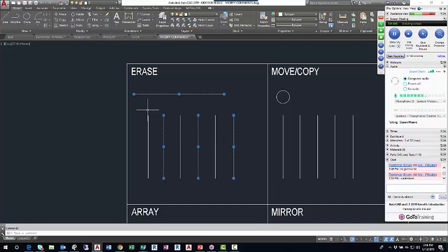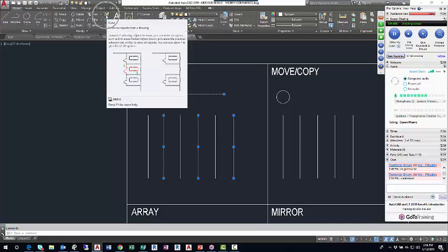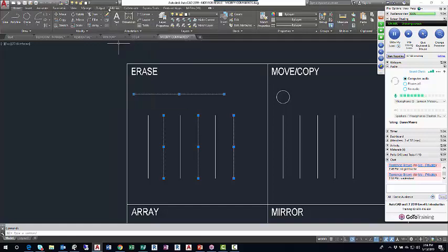With all my desired objects selected, I'll press the erase button on the modify panel. It looks like your Fort Ticonderoga #2 pencil. It's yellow with a red eraser. And if I left click on that, those 4 lines, my command line tells me erase 4 found. So erase 4 objects. I'll undo that, right? So it was just left click one object, left click the next, left click the next. And when my desired number of objects are selected, I'll hit the erase button.